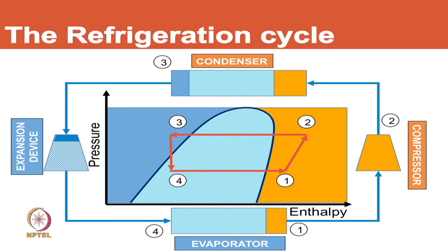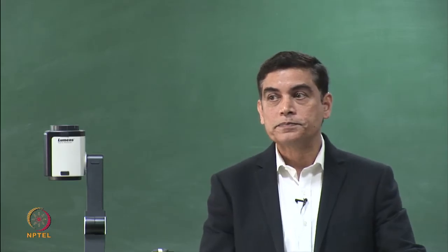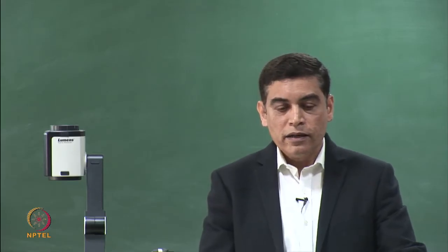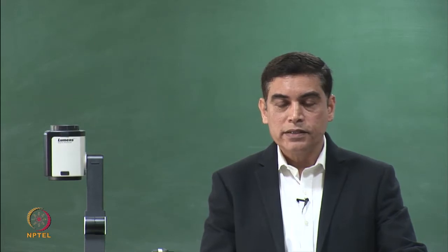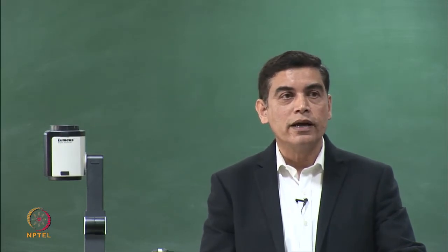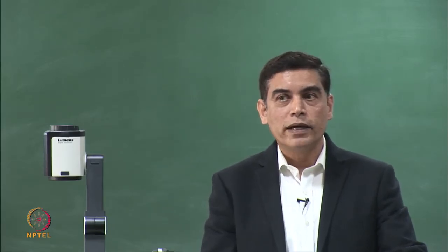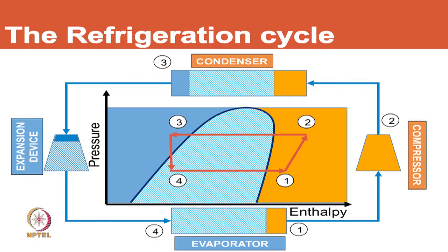The compressor operates in a vapor state, compressing vapor of the refrigerant. The attempt with all the controls and components that we select is to have the compressor always operate compressing vapor. Then we go to the condenser, and inside the condenser we have de-superheating, which in the next slide we are going to look at on a pressure enthalpy diagram, followed by condensation followed by subcooling.